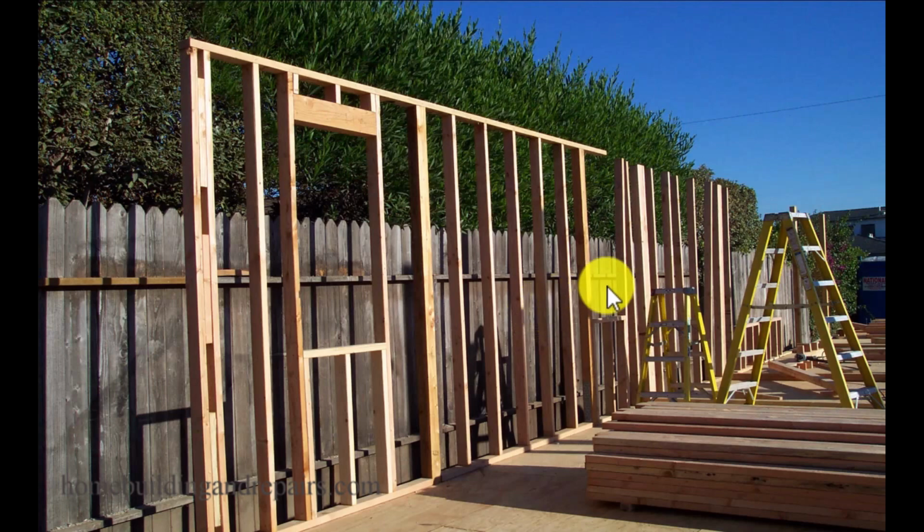And the reason for that, if you can see, we have 4x4s over here, 4x4s that have hold downs bolted to the building foundation. We have a raised floor, and I thought that it would be structurally stronger if we could bolt the 4x4s to the building foundation instead of setting them on top of the wall framing plate and then using a longer hold down or some type of connector to connect it to the building foundation. And hopefully that makes sense.